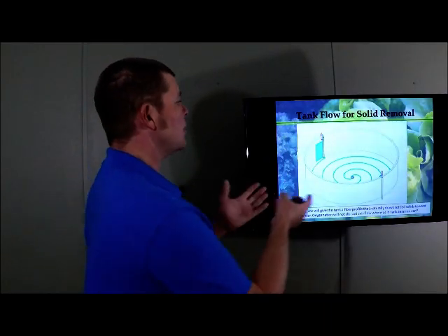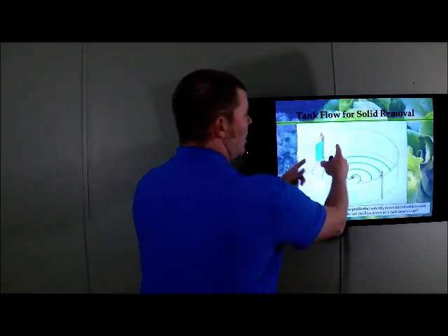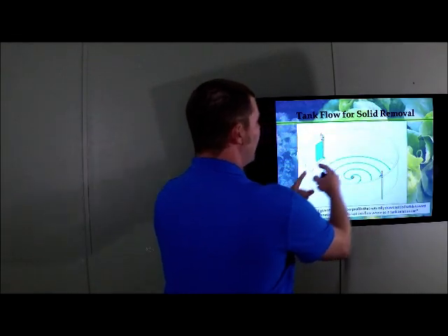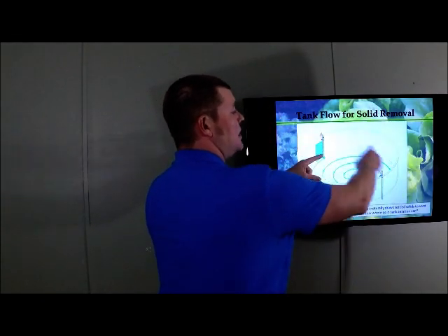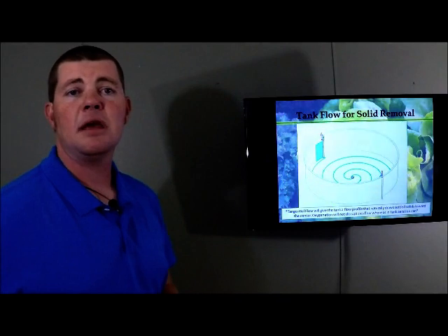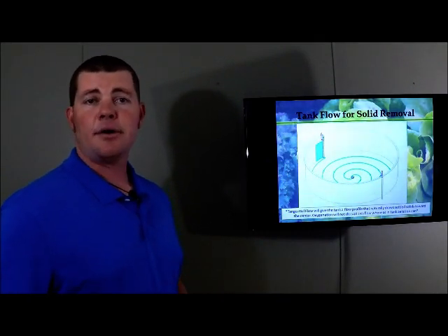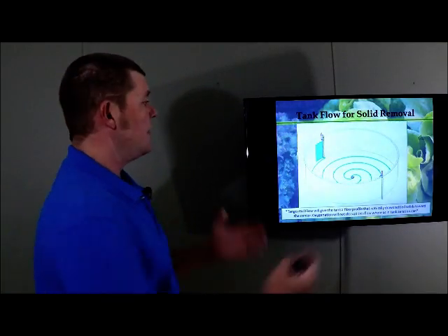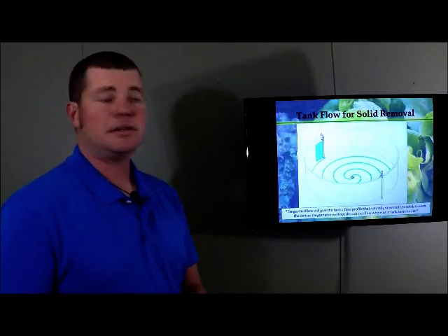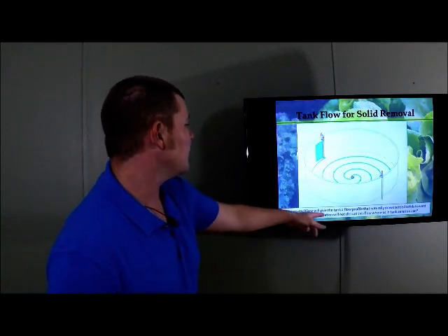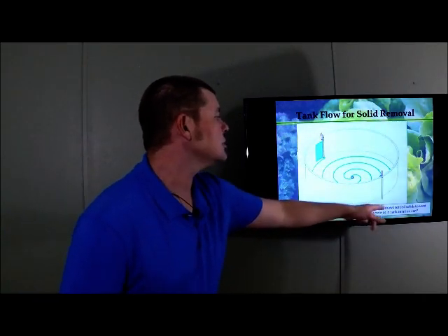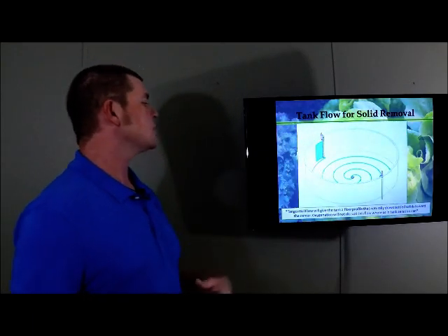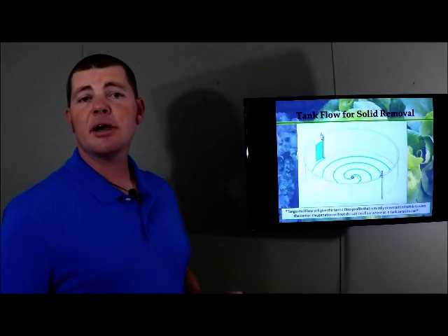Now if we employ aeration into this tank, say down the sidewalls, that creates an uplift current wherever we have an air stone, and that interrupts the circular velocity that we've created within the tank. It interrupts the tangential flows and it interrupts the radial flows that help draw that waste to the center. So again, at the bottom, tangential flow will give the tank a profile that naturally draws settled solids towards the center. Oxygenation will not disrupt this flow, but in-tank aeration can.